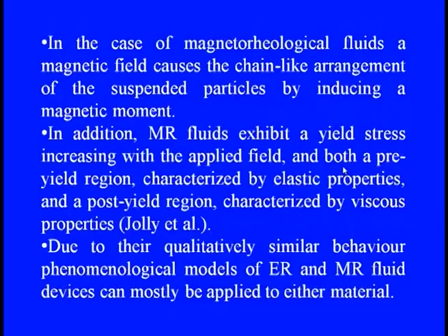So, in the Joly et al. paper, they simply show that when we want to see the elastic, the viscoelastic and the viscous features, we can see exactly what the pre-yield and post-yield regions are and how the behavior is there. Due to their qualitatively similar behavior, which is simply the phenomenal mode of ER and MR, we can say that these devices can mostly be applied to either material.